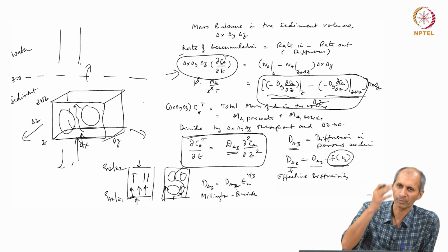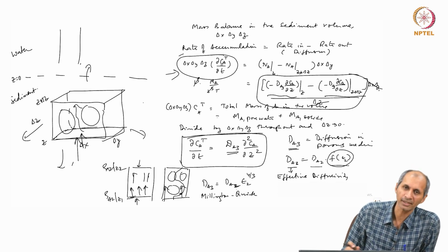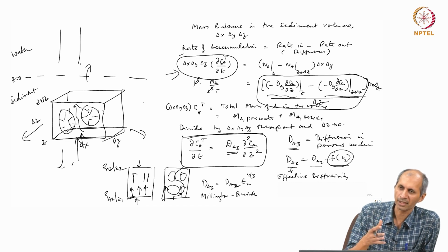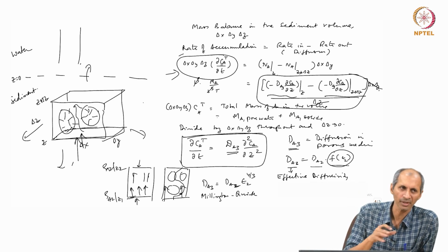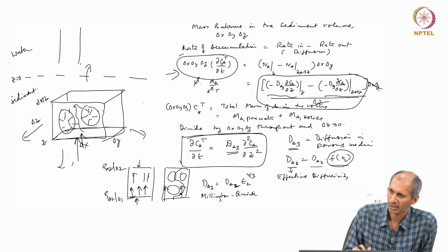Processes inside porous material are very complicated, especially if the solid has internal porosity and all that. So here we are not assuming all that. The internal porosity means there are pores inside the solid here, and the diffusion is not a straightforward process. It can go in, it will take a long time for equilibrium to be achieved, all those things are there. So adsorption and desorption are very complicated in these systems. So we simplify it so that we can model it reasonably easily, and we use that as a starting point. Okay.